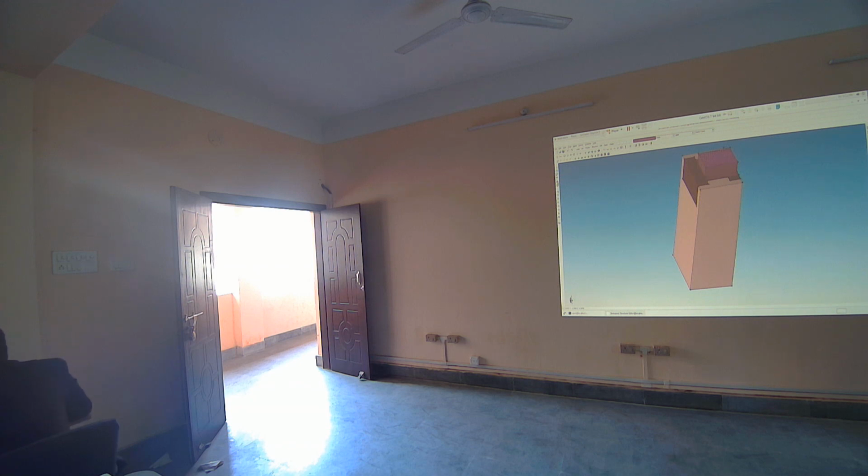Now I will turn this device upside down so that I can add the contact at the substrate. Again, we will do the same thing. Face, which is being already selected. If you have selected, it is already been selected, right? So click on this select, right click here, contacts and substrate. The two contacts have been added here. The first one was gate, and the second one was substrate, right?